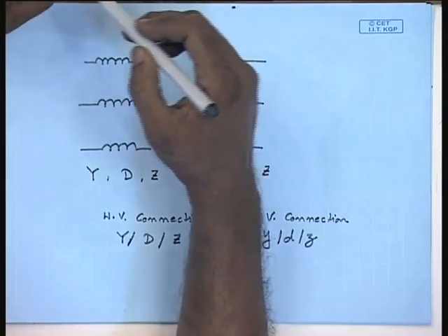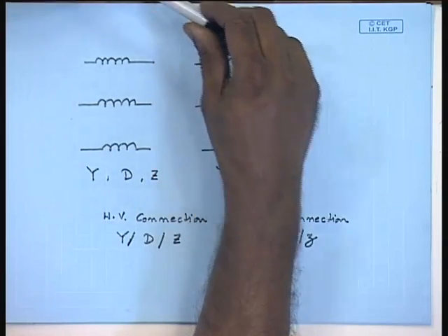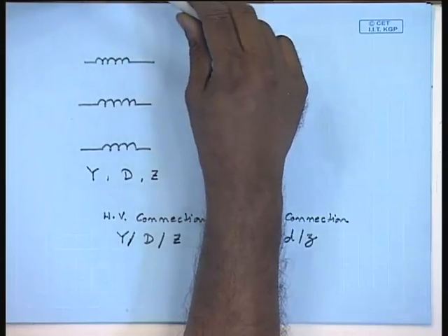However, that is not sufficient. In our last lecture, we have seen how to find out the line voltage and current as well as phase voltage and current conversion ratios of a 3-phase transformer given the winding turns ratios. So, we have seen that the voltage magnitudes on either sides are different. That is the purpose of the transformer. However, a closer scrutiny will reveal that not only the magnitudes of the high voltage and low voltage sides are different, in many cases they are also not in phase.